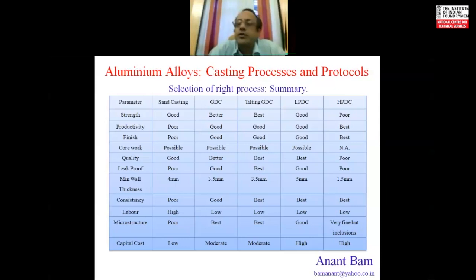I need not repeat each and every word. It is self-explanatory. There is one common question which everybody asked me in my every earlier presentation. That is why I said quality of casting is poor in case of high pressure die casting. Because vacuum HPDC is a recent advancement and it is available with only 1 or 2 parties in India. Otherwise, every HPDC casting is a leaking casting.